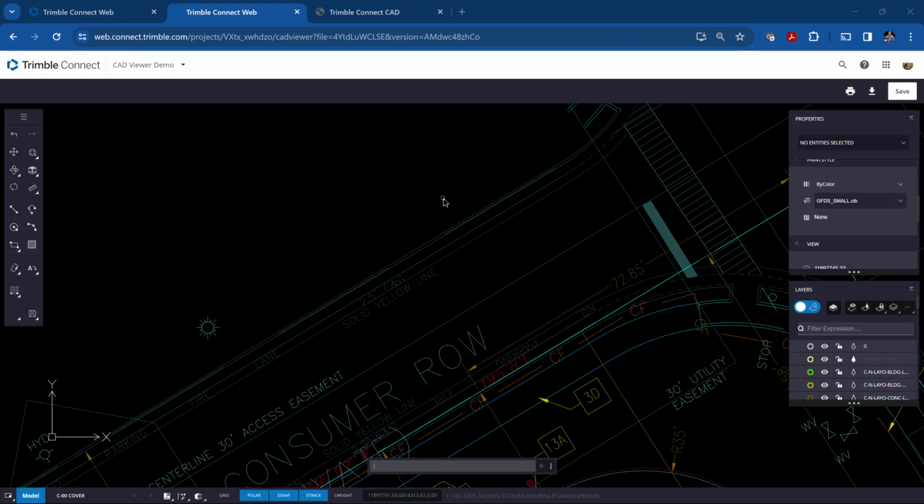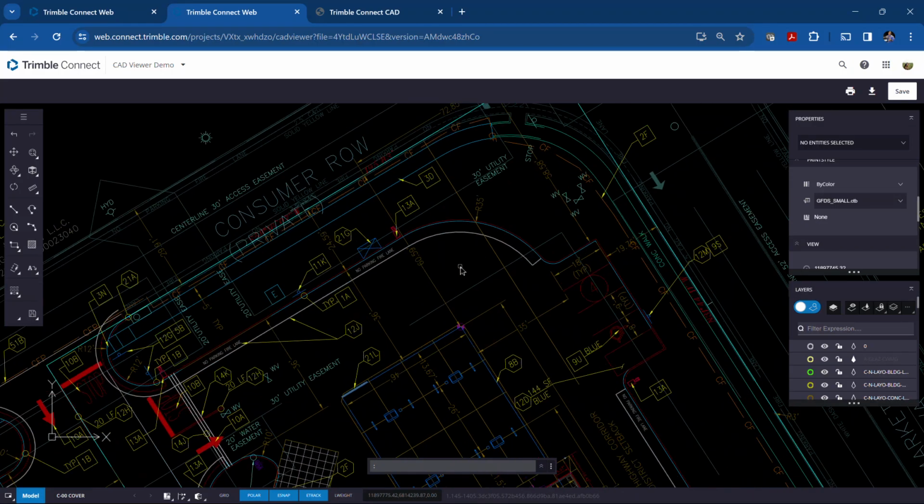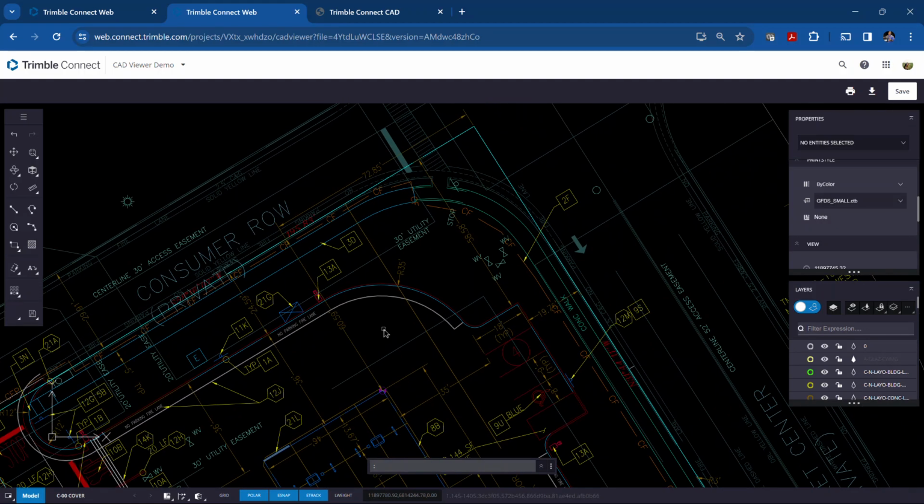All right, so the next object we're going to consider is what we call a special object. You can draw a line from the start point to the end point, and it's basically going to create a dot. Well, a point has a little bit different functionality and features, and usually points would be used if you're staking out, where you want to put a point for a stakeout of a radius of a curve, or maybe it's a control point.